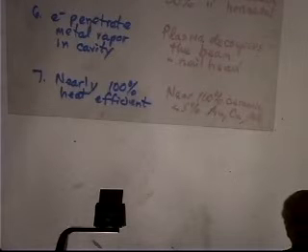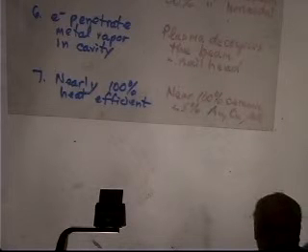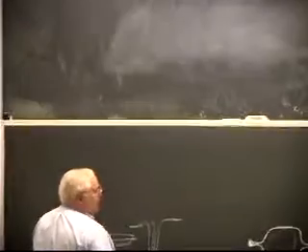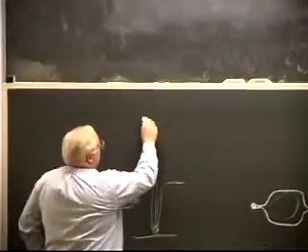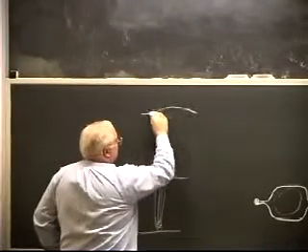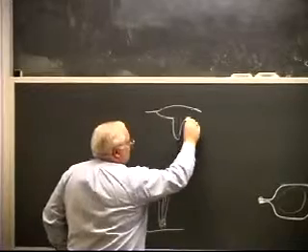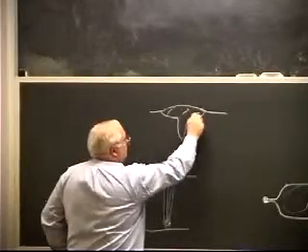The problem with the laser is the plasma. The photons will cause some heating of that metal vapor, which is pretty hot anyway. If there are any free electrons, those free electrons will absorb some of the photons and re-radiate them, and you'll get decoupling. In fact, you get what's called a characteristic nail head shape, which you see in both electron beam and laser, but it's more common in laser. You'll get a weld pool that actually looks like this, and they call this the nail head up here.